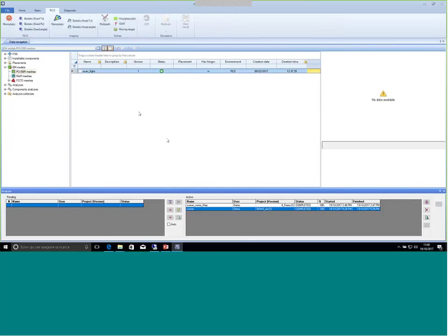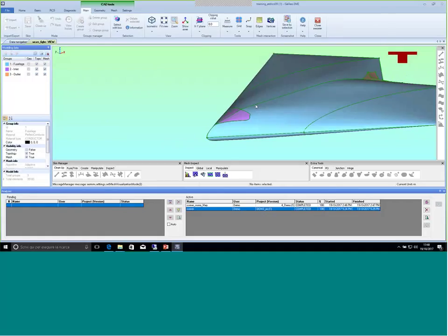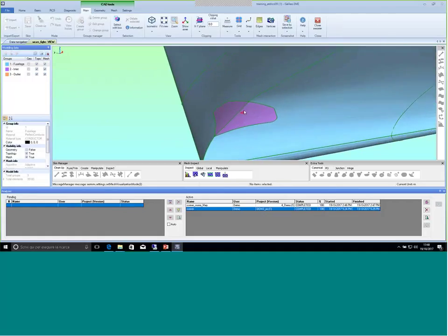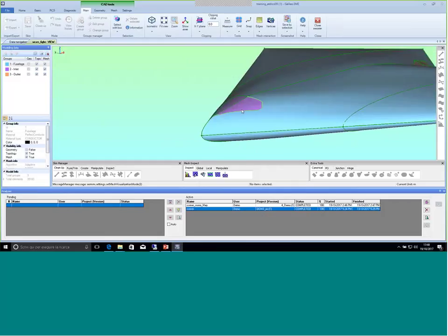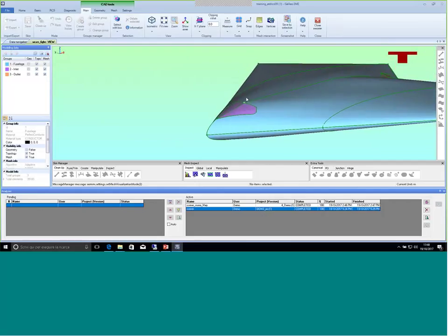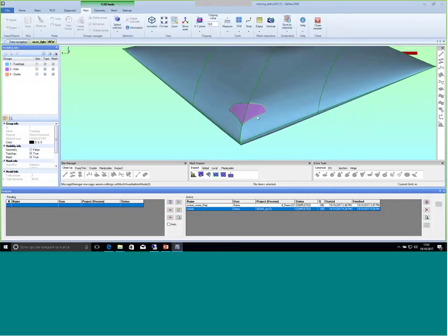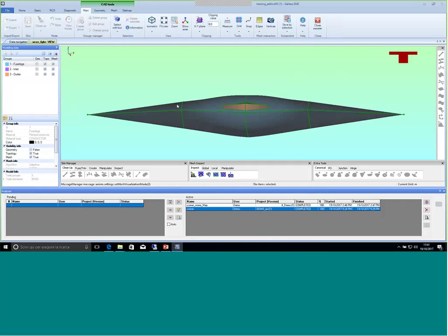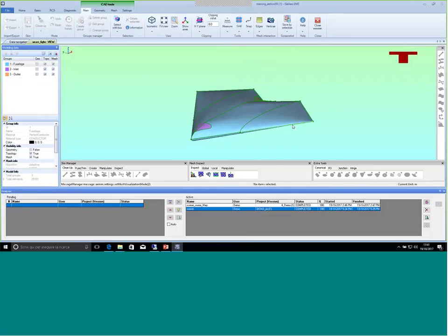For the external fuselage, I have computed an asymptotic mesh model, and according to the same principle like for cavities, I need to remove the external contribution of those structures. For the fuselage with cavities, I need to remove the contribution that comes from this part here. And for this reason, I have installed here in the interface of the inlet a perfect absorbing material. So I don't get any RCS from the inlet interface and from the outlet interface, but I get just the scattered field from the fuselage of the aircraft.